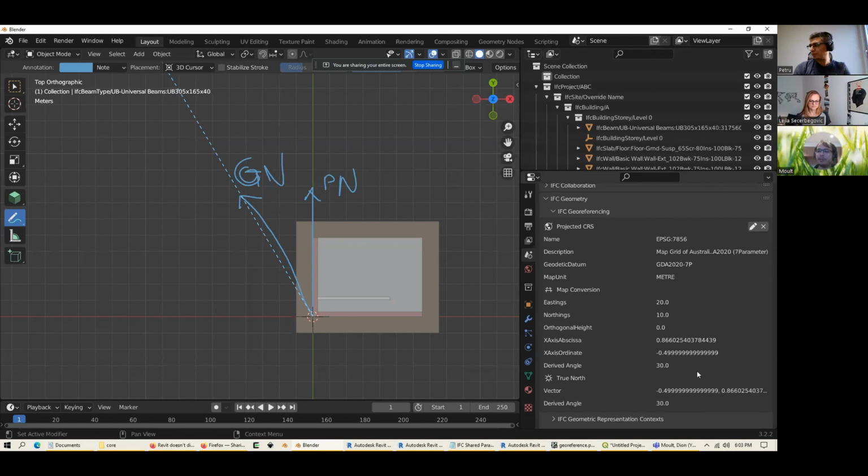We've now covered the rotation. I just want to mention that that's not all. There's actually this next step, which is also missed. I kind of see there being a number of common misconceptions around geolocation. Some people are aware of the true north and the grid north difference. The last one is something that very few people are aware of, but it's also vital in how surveying works and how IFC works. And this is known as the scale attribute.